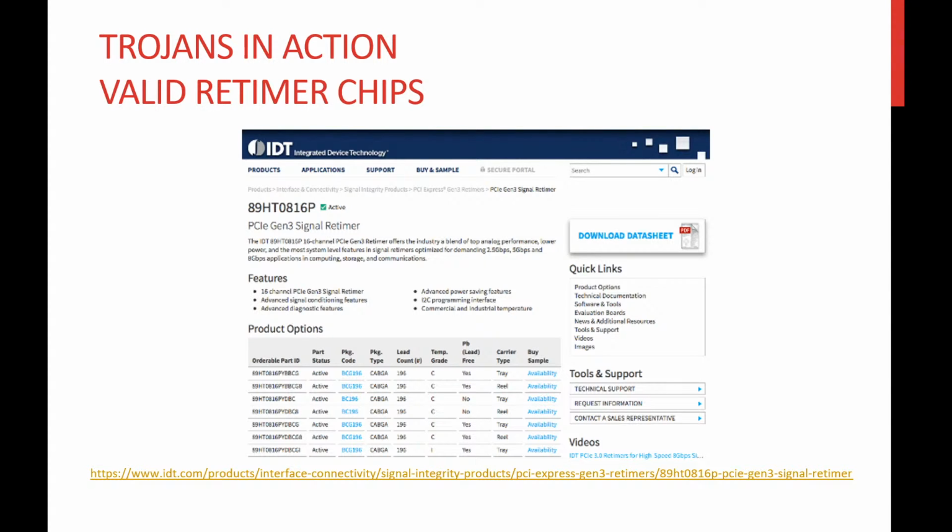Fake products or counterfeits can have several levels of fakeness. They can be real products reclaimed from discarded electronics and cleaned up, so they are real parts but have some lifetime used up. They can be real parts but repurposed for other bins, such as a 3-core or slow part being repackaged and sold as a 4-core or fast part. They can be real parts but reclaimed from discarded or failed parts from the manufacturing process. So for example, they may be parts that were rejected for stuck-at faults, excessive current leakage, or delayed timing